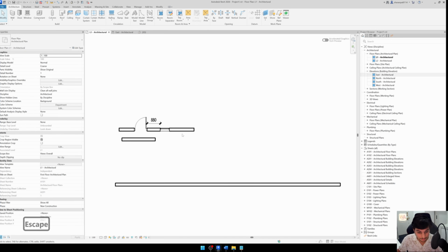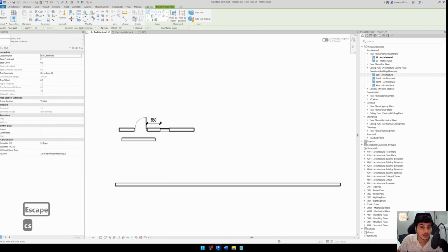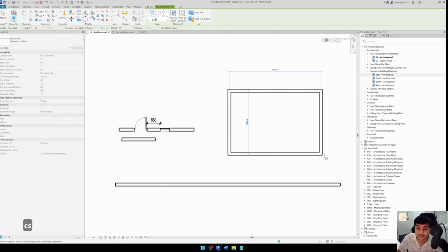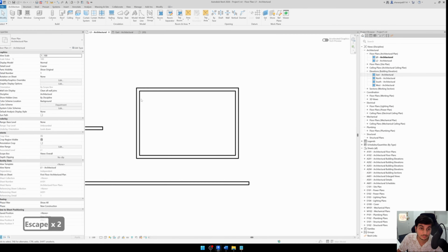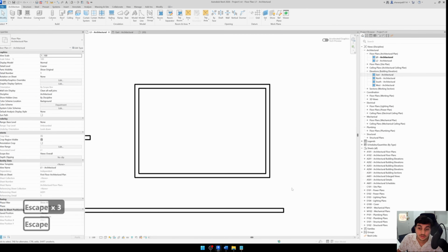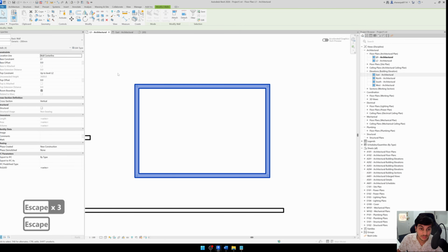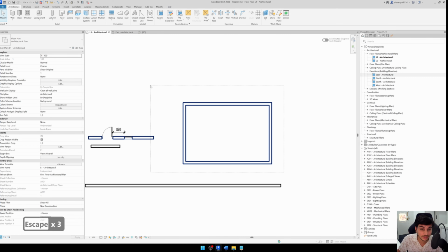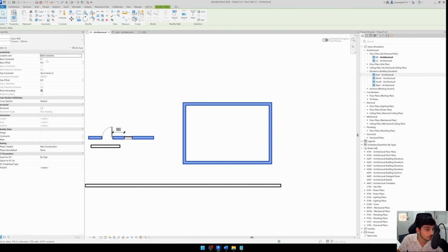So now I'm going into selecting a wall. Okay, now I'm drawing a rectangular wall here for now, so that I can place a floor in between. Okay, now I need to define some height. So this is running from level 1 to level 2. So now I need to define the height. This is running from level 1 to a top constraint of level 2, which is accurate.